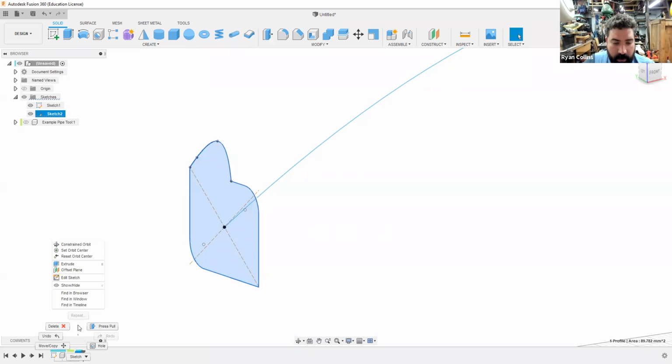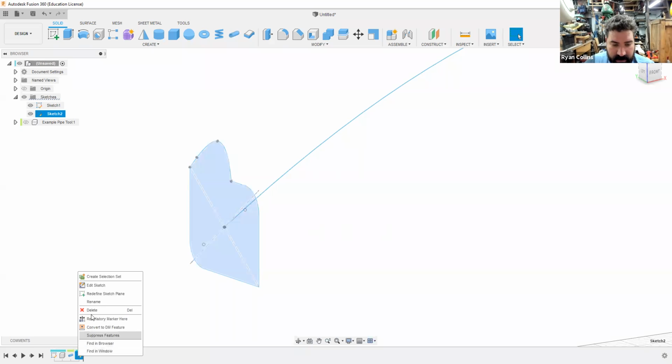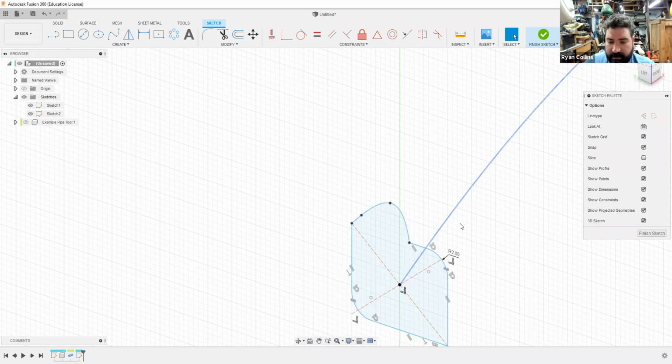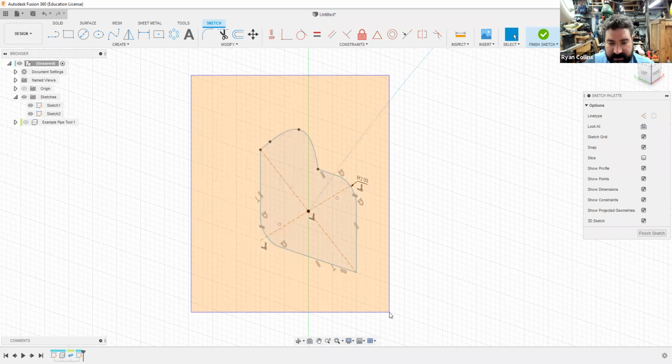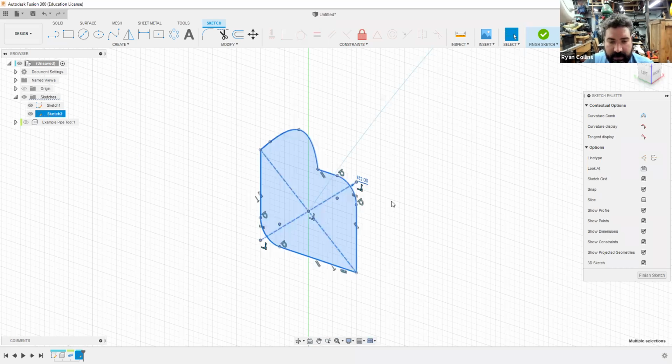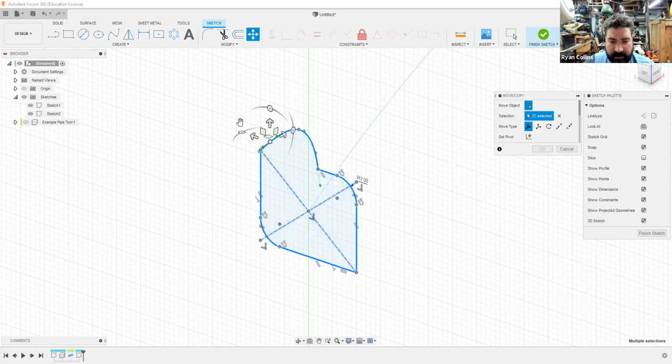What I do still want to do is rotate this though. So go back and I'm going to open the sketch back up. Why does it keep doing this there? There we go. Hit sketch, rotate around just like I had before. Use a selection box. There we are. Use the move tool. Now, if it throws your center of orbit way up here, remember you can reset that. I'm going to use the pivot, set pivot, select that on my toolbox, select smack in the middle there. Now, done, uncheck that box.